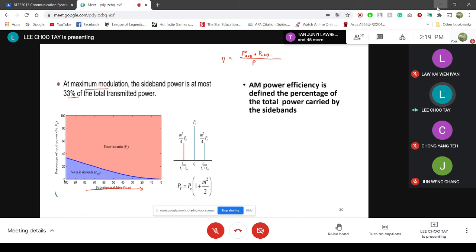At 2 times my cutoff frequency, that would be per octave, so I have another 3 dB, so 6 dB attenuation.